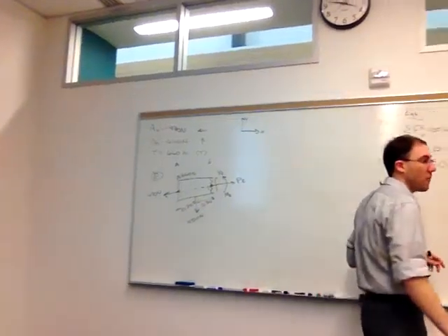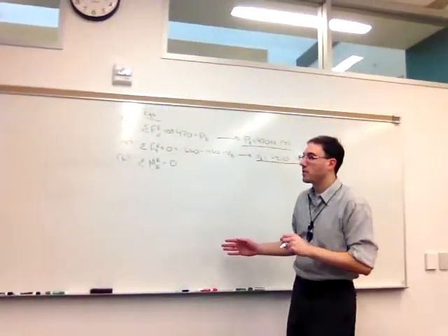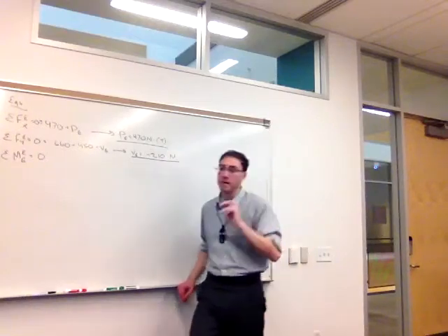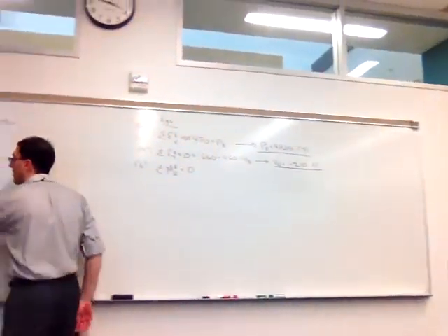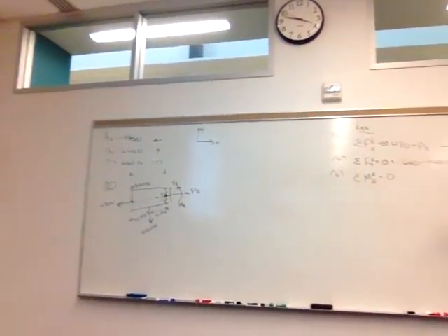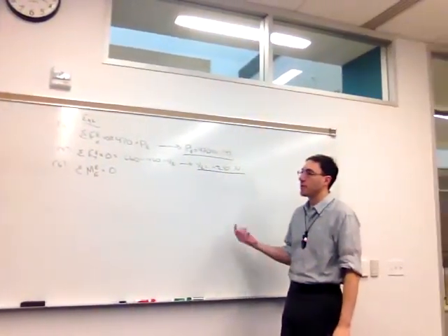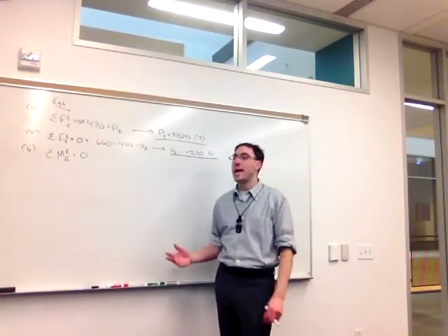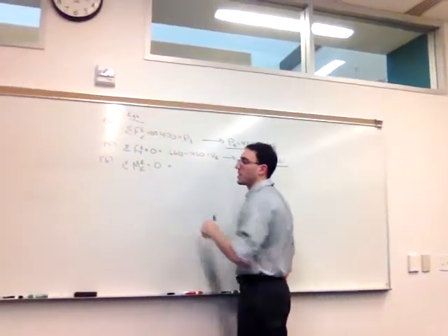So usually I'm going to be ignoring or assuming that all of those lines of action pass through that. So when I take the sum of moments, I'm going to say the 470 newtons does not contribute to the sum of moments around point E, again, point E specifically being the centroid of the beam. So PE does not contribute, VE does not contribute. I'm assuming the 470 contribution is 0 or negligible. So what does contribute?